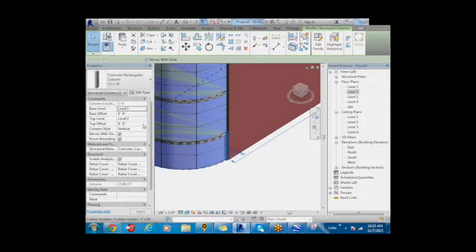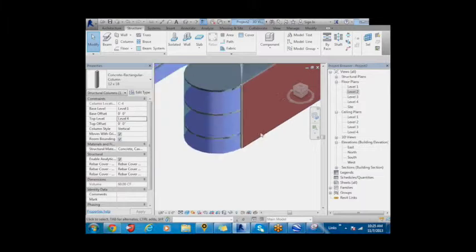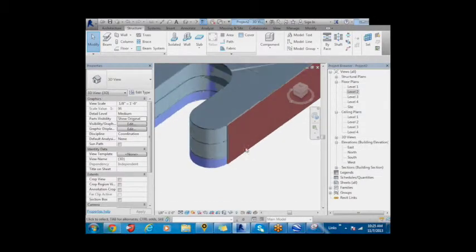But I think for real structural engineers, some of you can correct me if I'm wrong, columns typically get smaller as they go higher in the building because the load reduces as you go higher and increases as you go down in the building. So you might want to change the column section as you go higher. But for the purpose of this class, you could as well just increase this and it should go all the way to the top. So that's pretty much it for adding columns to your conceptual mass building. So the next step, if there are no questions.